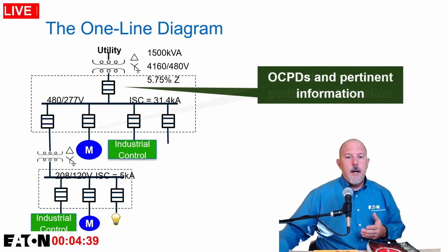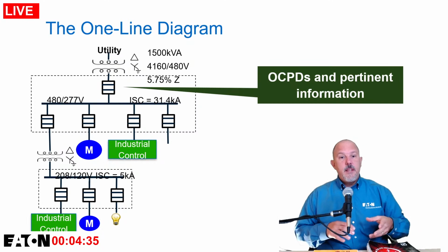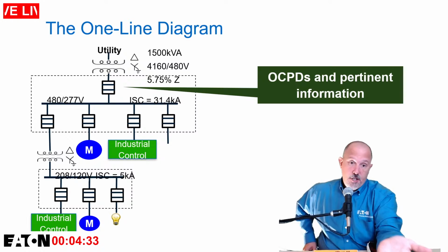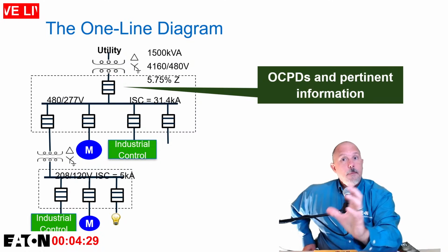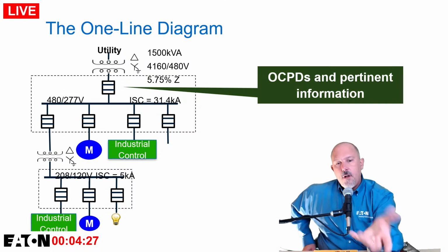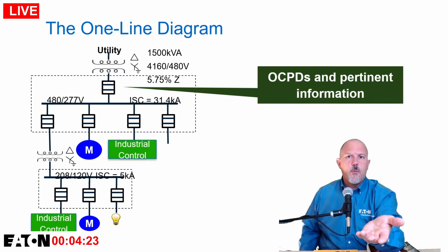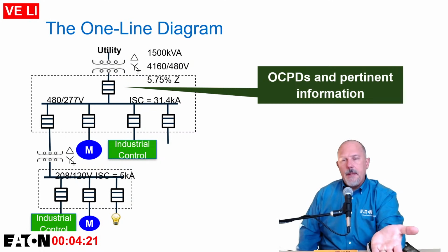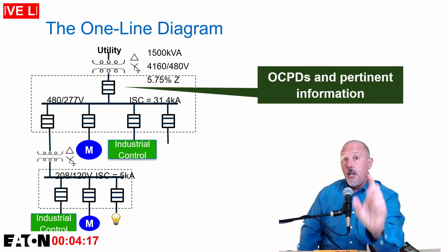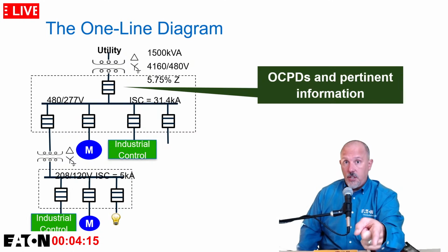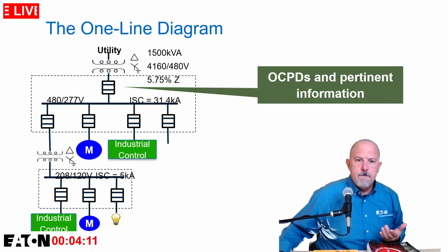Okay. And then in your panels, typically some of that information might be in your panel schedules. So in a panel schedule, you might have your HVAC loads, which are too small to be putting on a larger one-line diagram. You'll go down to the panel board, and then you'll rely on the panel schedule to give you the detail on the loads associated with each of those, whether it be lighting load and things like that.